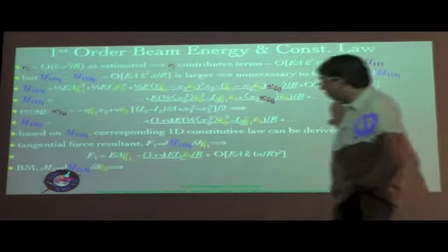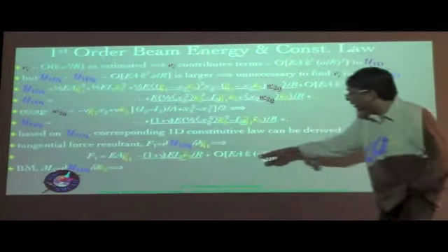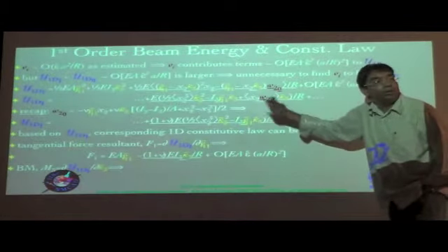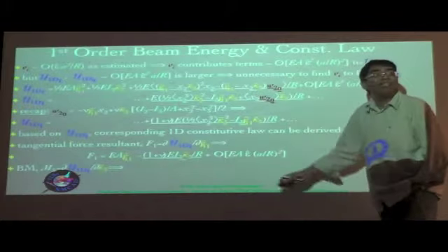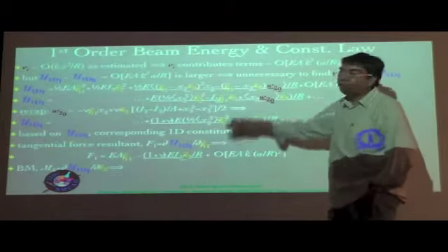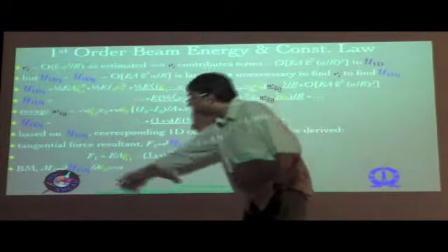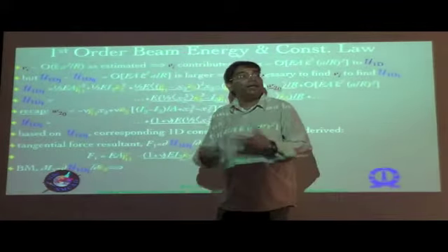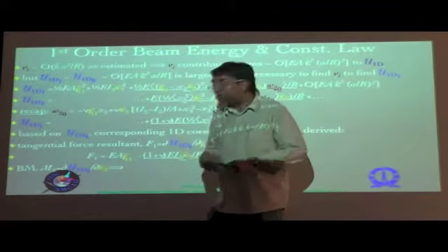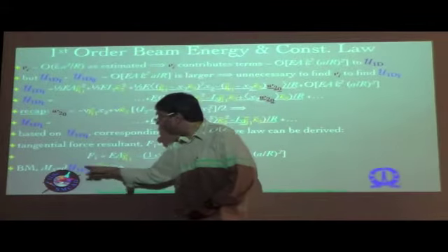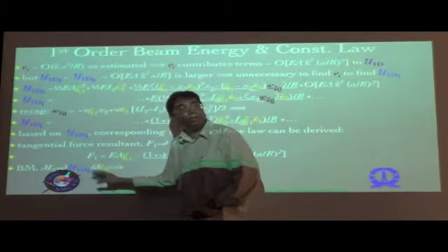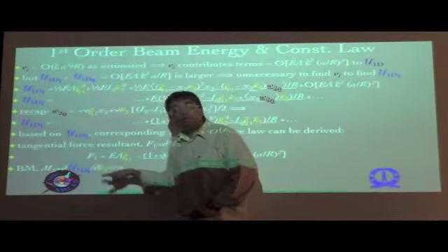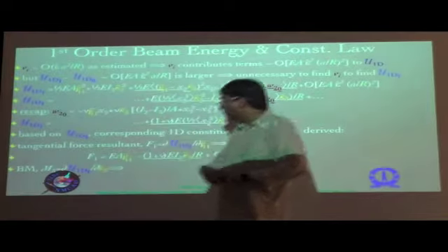So now let's talk about the bending moment, and again here you have the higher order terms, which can, if necessary, be determined by going to higher orders of approximation using exactly the same procedure that we followed for the first order approximation. So when you want to determine the bending moment M3, which is again an internal stress resultant, that will be a partial derivative of energy per unit length of the beam, approximation at the first level, with respect to the bending curvature kappa 3 bar.